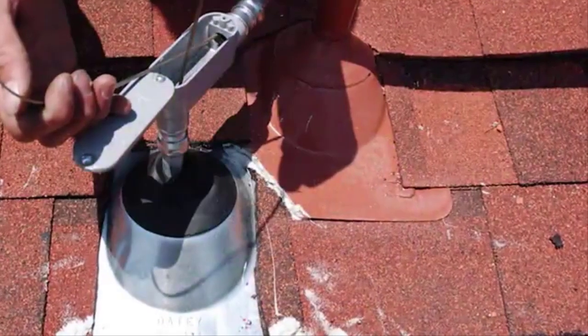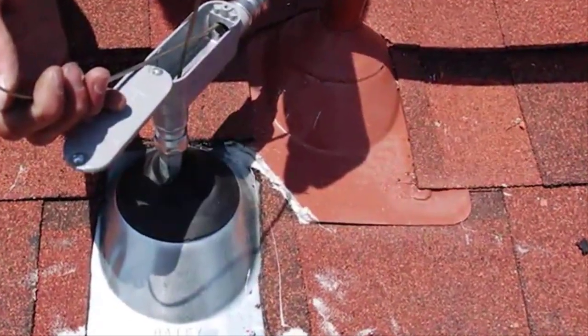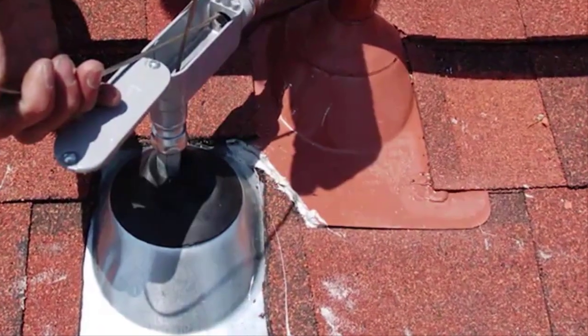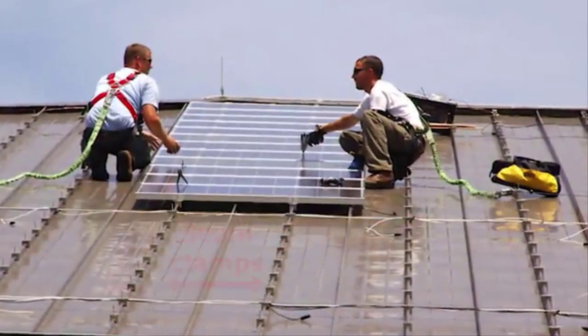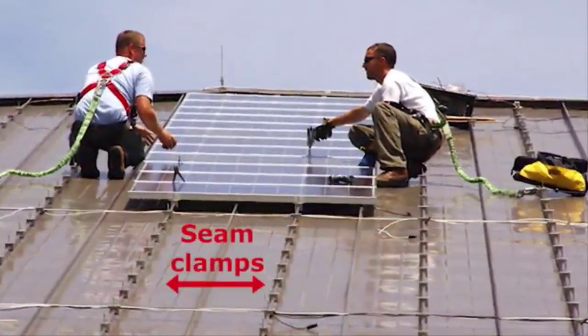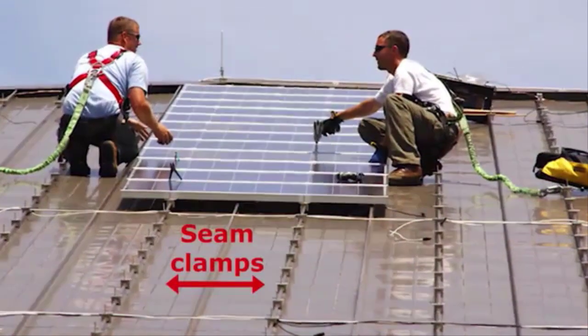All of the weight considerations need to be addressed by an engineer and/or architect before proceeding with installation. Waterproofing systems protect the roof and building from water penetration using rubber gaskets and sealed boots. The mount points are then lag bolted into rafters, thus connecting the system from rafter to module. In the case of a standing seam roof, a metal seam clamp attached to the rack and then to the roof prevents roof penetration. For flat roofs, one of the ways to be able to attach the panels is to